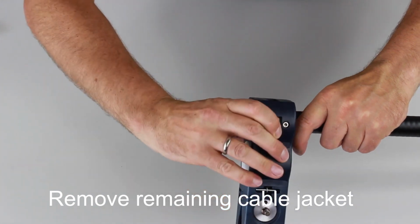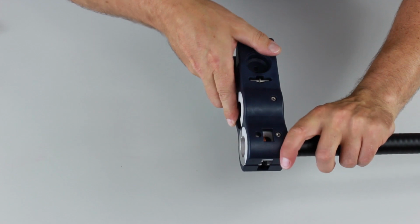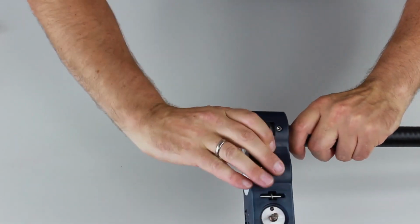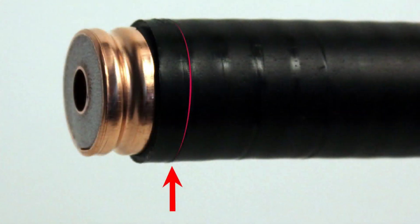Using the peel insert on the Uni-Prep tool, peel the cable sheath back to the previously formed sheath cut by turning it around the cable and then remove any residues.